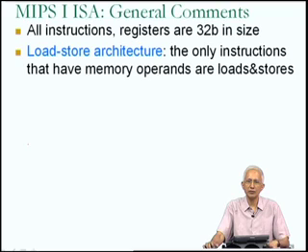All of the other instructions take operands out of registers, and this is going to help to make the instruction execute faster. There is no need for those instructions to wait for an operand to come out of main memory at 2 orders of magnitude slower speed than the processor, as we had seen a few lectures ago. So the MIPS1 instruction set is a RISC load-store instruction set.